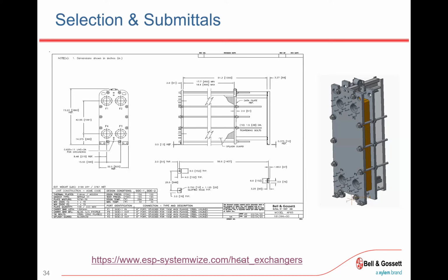So if you do have something like pool heating, or something that's a bit more aggressive for a fluid, titanium's usually a great option. 316 is all right, but at the same time, it has its challenges in comparison. But obviously, there's a cost included with the titanium. That's a bit more of a premium.